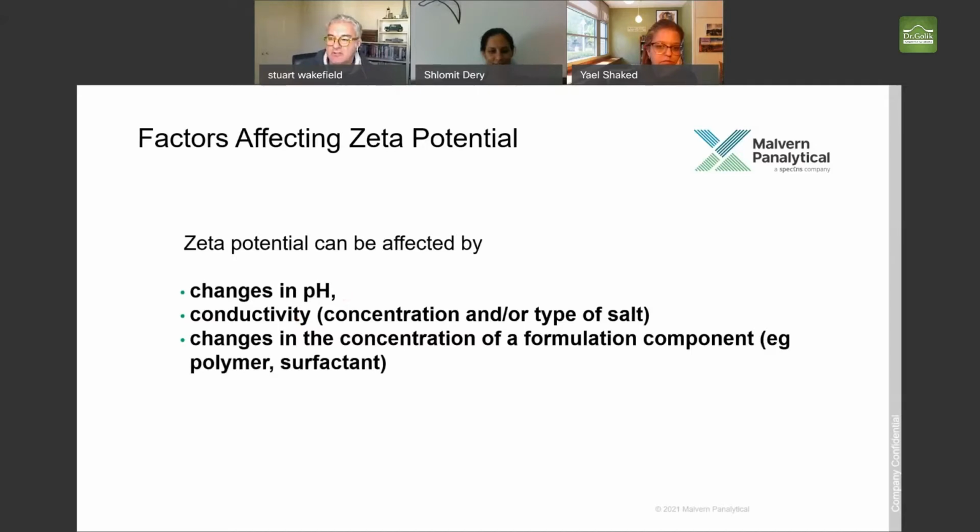We know that the concentration and type of salts present are changing as well because of that. And we know that adding chemicals, electrolytes and polymers, etc., to the water is also going to change the Zeta potential. So based on just those 3 things, it's actually a very powerful tool and parameter to measure to understand your treatment process.